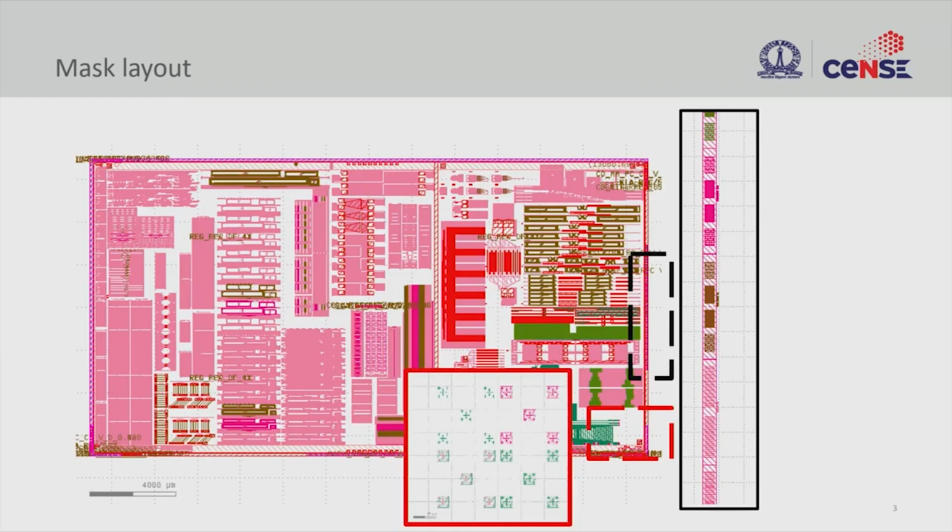So this is a GDS file, or you can say a design file that has a lot of features. We have a circuit here with different colors showing different layers in lithography, and this is the design that any circuit designer will come up with, and we want to transfer these circuits onto the wafer. But there are some interesting features on this mask. We saw earlier that we want to align the masks of different layers, and we use some alignment structures. This is a zoomed in picture that shows these crosses and boxes. We saw earlier how we align it, the alignment of this cross with this type of structure between two different layers. That should give us an alignment between two different layers. So this is also put on this mask.